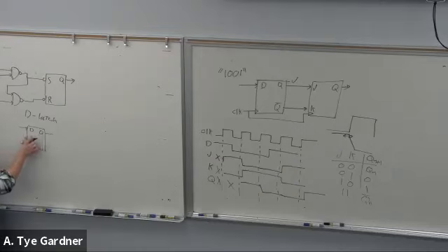So it could be things like, once I have these, I may end up showing you guys what this device is, and I would draw two D latches connected together, right? And that's how we build the flip-flop. It takes two D latches. And I could do it even at this gate level and connect two of these together to make a D flip-flop and ask you that kind of device. It's just being able to recognize how these building blocks built up from that lecture, right? That I went through and built from an SR latch at a gate level all the way up to a D flip-flop.